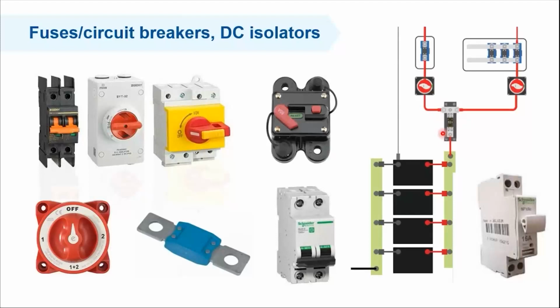And there are time ratings for the fuses as well. So no matter if the cables for a short time are getting 1.5 times the maximum current, it will then blow and trigger, and the cables will be safe, of course.